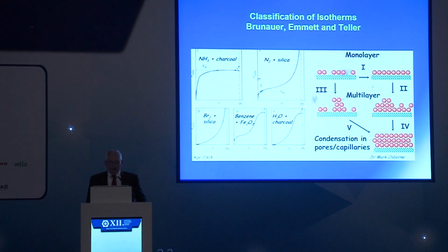If we look at a desiccant, they're always classified in terms of the BET, or Brunauer, Emmett, and Teller, isotherm shapes, 1, 2, 3, 4, and 5. Many times we'll usually be looking at 1, 3, or 4. Type 1 is typically a strong adsorber. If you read the literature, there has been a lot of discussion about what's called a type 1M modified, which is not quite as strong an adsorber. You'll see a little bit of water on different sorbents, type 4, and type 2 desiccant.